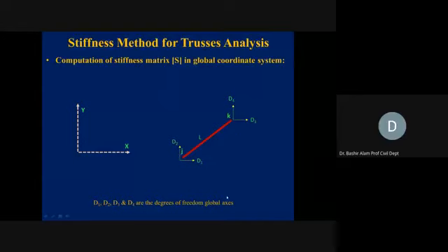Why? Because here at K it is hinged and it's a surface adjacent to this. So when you start pushing it to the right, shortening is going to happen in this element. Why? You take the example of when you drag it, let's say it is coming under this joint K. So this vertical distance is less than this diagonal one. Why is it less?